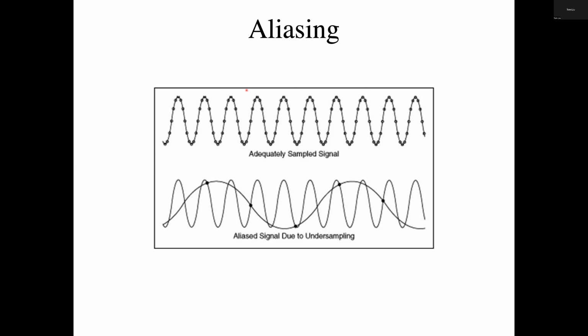And so that frequency would be a point at not one full cycle of this sine wave, but at a half cycle. So you need 2 points per cycle, right, in order to sample it correctly. And that's called the Nyquist theorem. And we'll look at that in a little detail.